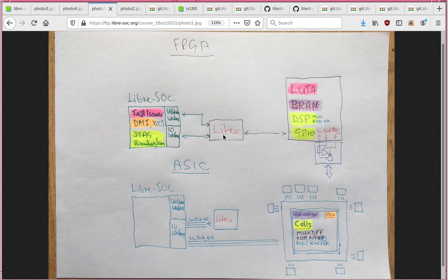They get thrown to the tools, and the tools generate the cells and the resources, and a bitstream which will conform to everything that's needed. That's handled by LiteX, but there are several other tools as well. Nmigen itself can actually target a huge number of FPGAs, with the different platforms on which those appear. Also, in the FPGA you have a PLL block.